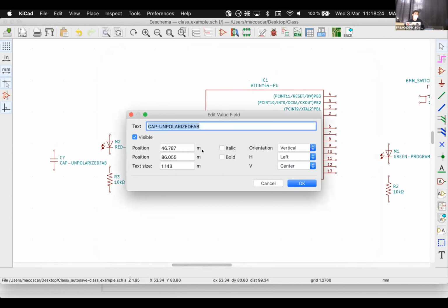Be careful if you do these things outside of the academy with more complex electronics, but 1 microfarad is a good value for a filtering capacitor in the input of any microcontroller, okay? That is the normal. You would have to check the data sheet of the microcontroller or the component that you're using, but it's a good normal value, okay?